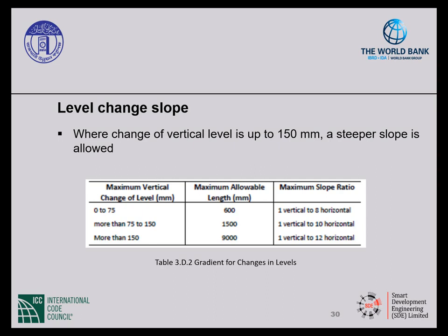Since some ambulant disabled persons can maneuver steps and find that more convenient and safer, accessibility provisions for both ramps and steps should be given. In addition to these slopes, we will discuss additional requirements for the ramps and steps at a later time.